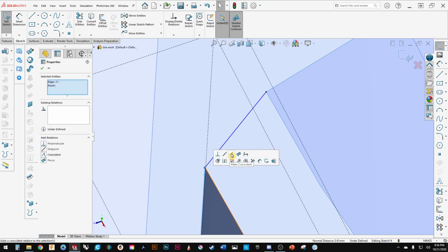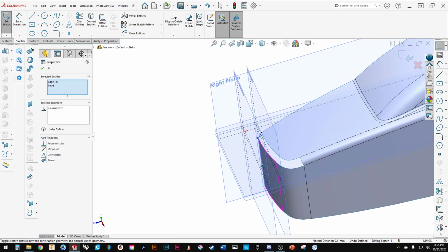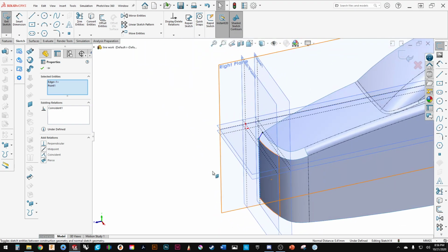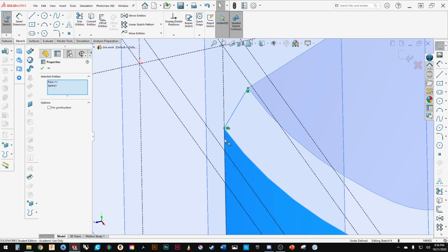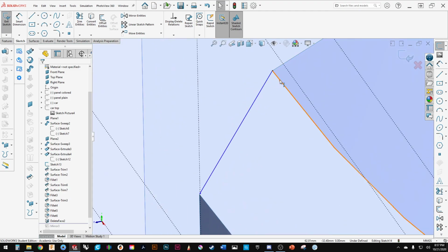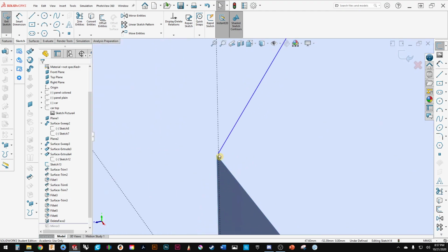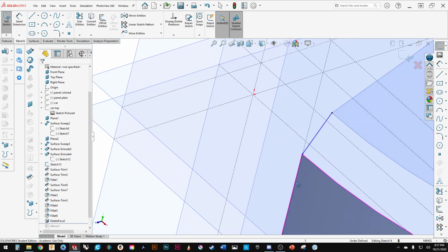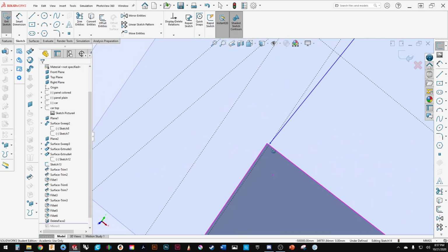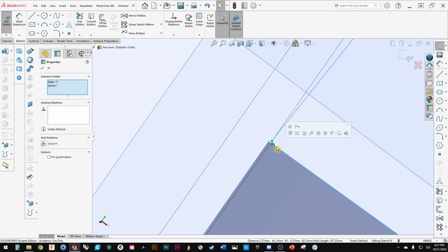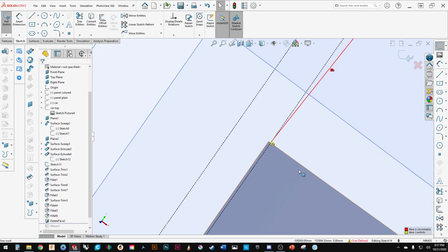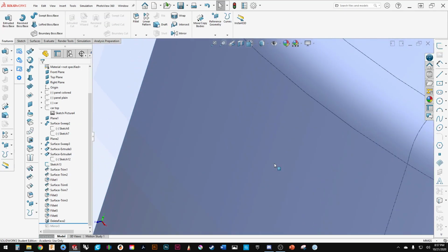But do you know what I'm saying? Like, is that front face sticking out further than the right plane? Oh, no, it's not. Okay. It's just, sometimes when you put radiuses in, it extends it beyond. So, but what I'm doing here now is I know where I want the radius to start and to finish. You're getting more of an exact profile. No, maybe, yeah, maybe you are right. Because that's the only reason I could think that it would connect the dots and make it stick out further. Yep, I think you're right. For some reason I did that.